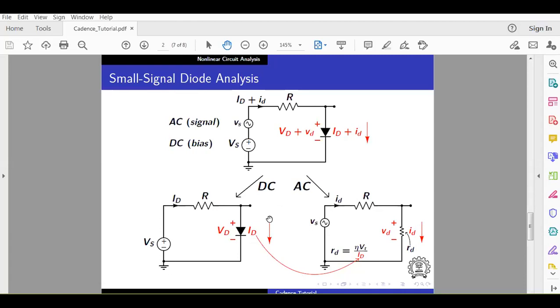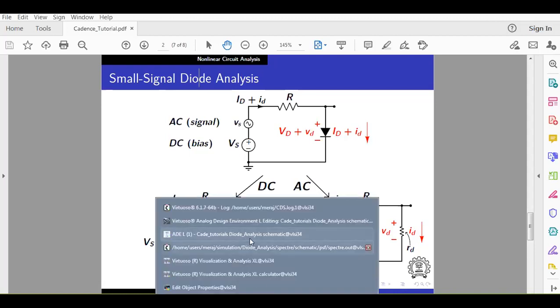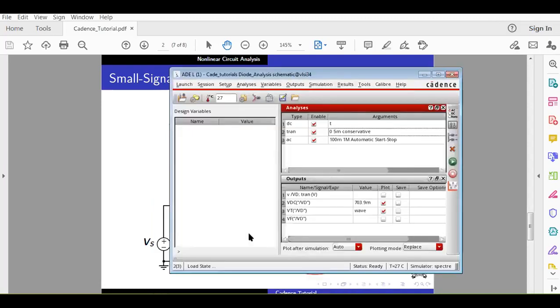But if it is a transistor or a diode in DC, you cannot apply a huge potential. So it's not a realistic simulation in which you are applying that. So any value is fine. Generally we give 1 volt because if you see the transfer function, output by input, if your input is 1 volt, your transfer function is your output. So it helps in many ways in analyzing the transfer function.